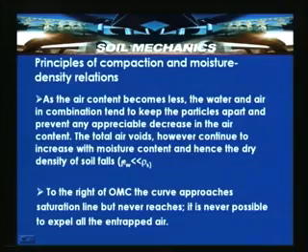So, what will happen is that when the water starts occupying the space between the grains, air and water are actually inhibiting the particles from coming close once we cross this optimum moisture content. So, the optimum moisture content is a threshold limit for that particular soil. Once we cross that, the particles will not come closer because of the presence of air and to some extent excess amount of water, which actually inhibits the particles from coming close. Another thing is also that the unit weight of water or the density of water is much less compared to density of the soil solids.